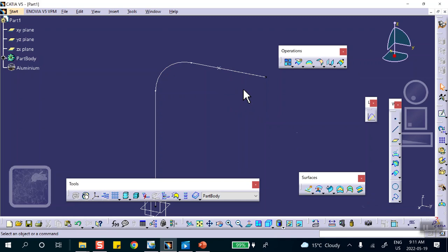You might think, okay, no problem. I'm going to mesh this thing, and then I'm going to apply it to that point. Will not work, because this point is on that curve, but there is no guarantee that there is going to be a node there. Remember, you set the size of the element. Even if there was a node exactly at that location, when you put the load on that point, it will not transfer to the finite element. I told you there's a few things you have to do. I created the point where I anticipate to apply the load later on, but that's not good enough.